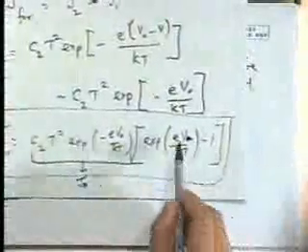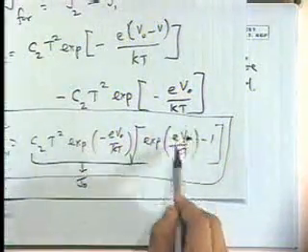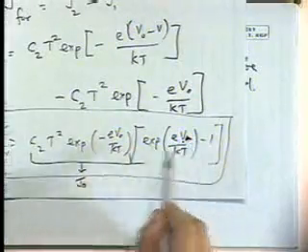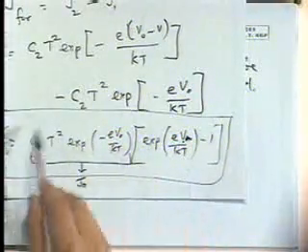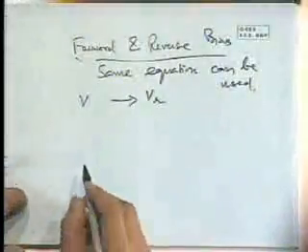It can apply in both cases as long as you substitute the reverse bias here. This is a very large negative term that you get in the exponent, and so effectively it will saturate back to this number. That's why it is known as the reverse saturation current.